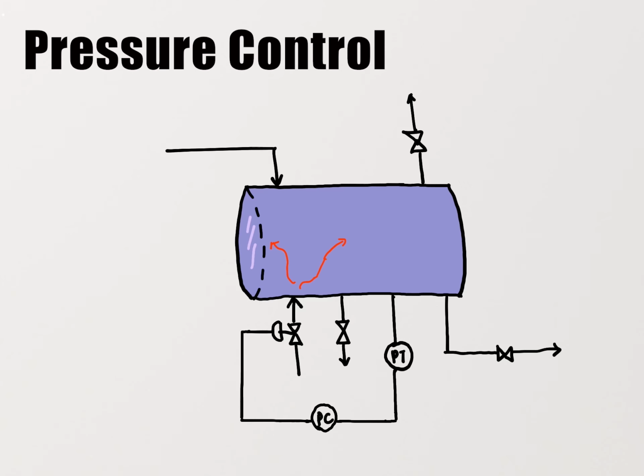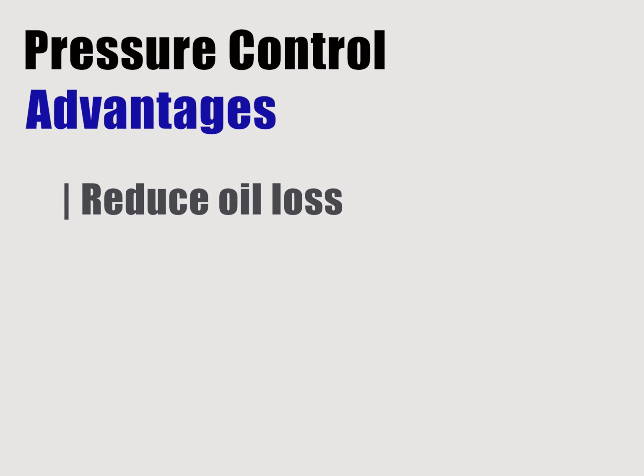During sterilization, the steam is trapped in the chamber. The pressure in the sterilizer is measured using a pressure sensor. If initially the pressure is lesser than 40 psig, the control valve of the inlet steam will increase the flow rate in order to increase the pressure in the sterilizer. Once 40 psig is reached, heating is stopped for the steam to reach 0 to 5 psig before being replaced by fresh steam. This control system provides only sufficient heating, as overheating causes oil loss. This control system also prevents oil loss that may contaminate the environment.